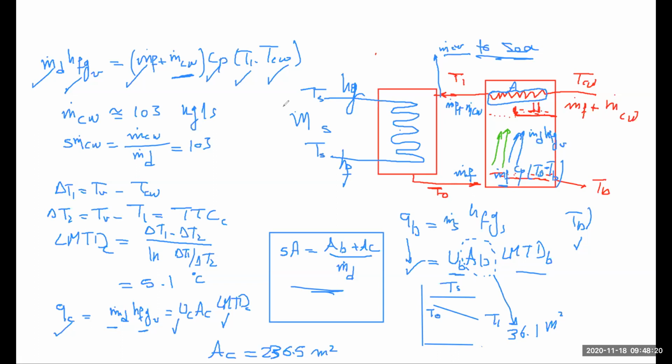That's why they put the alloy of copper and nickel together. They increase the quantity of nickel at high temperatures, or they go for another material with low thermal conductivity, but they use less thickness of the tubes, which is titanium. But it comes as a good solution for the high temperature side.